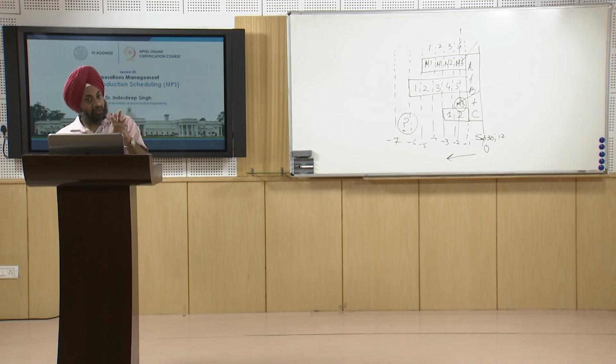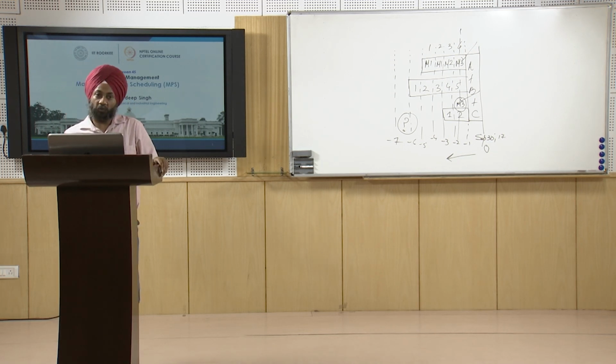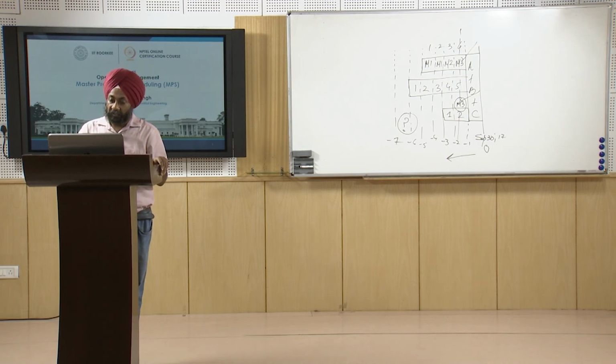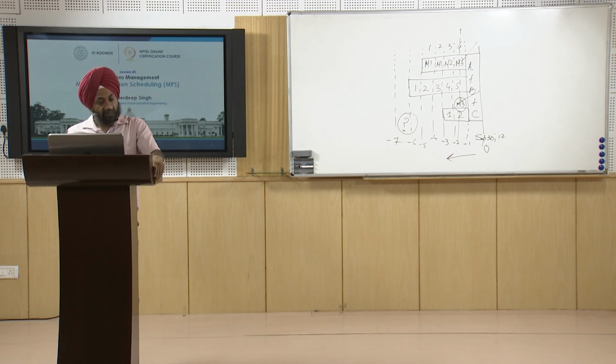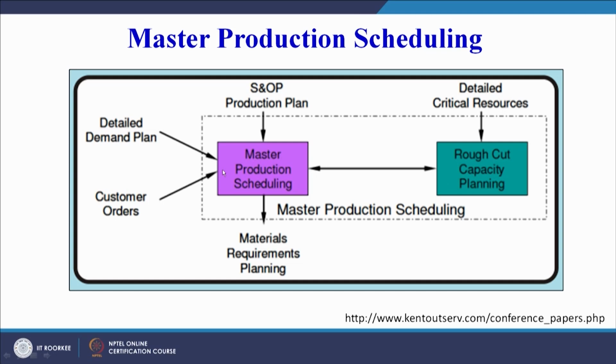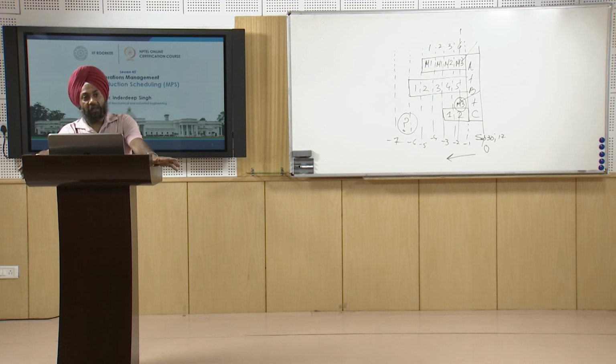So it is basically a production plan focused on the timely production of each and every component of the product, so that the product is delivered on the due date. So our master production schedule will be an input to the materials requirement planning system. So we can see the MPS is first tested, and rough cut capacity planning is done. So we know what the demand is, and whether we are able to meet that demand with the existing capacity available with us. If yes, go ahead, the final MPS is issued or prepared.